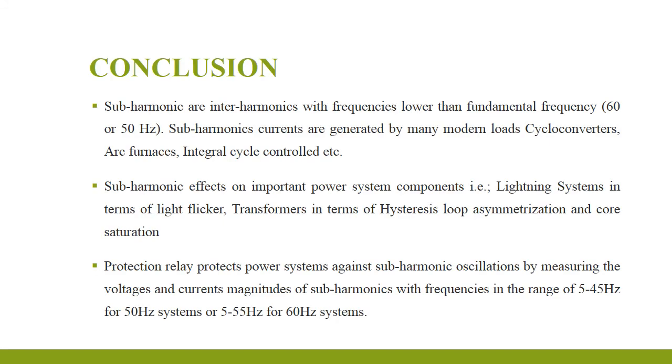Finally, the conclusion is here. Subharmonics are interharmonics with frequencies lower than the fundamental frequency. Subharmonic currents are generated by many modern loads: cycloconverters, arc furnaces, integral cycle control, etc. Subharmonic effects on important power system components include lighting systems in terms of light flicker, and transformers in terms of hysteresis loop asymmetrization and core saturation.